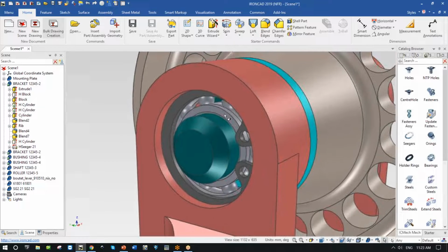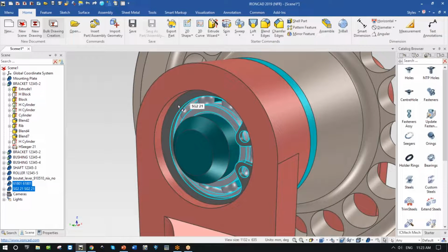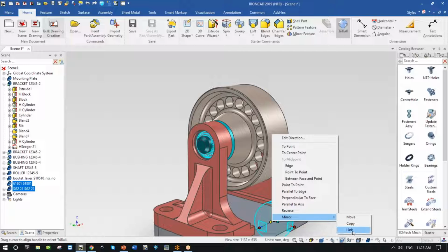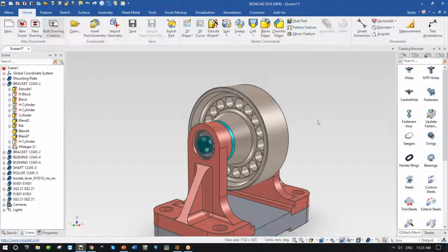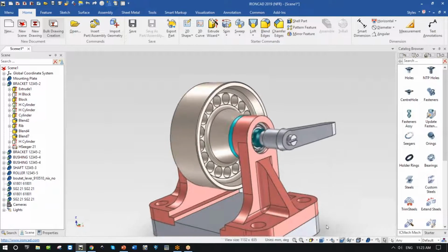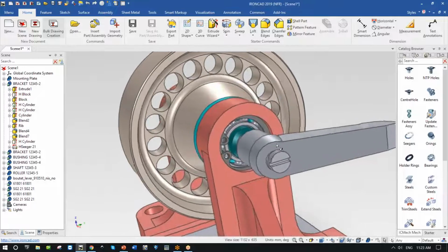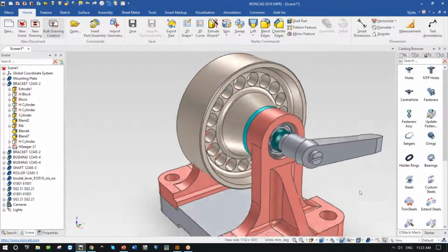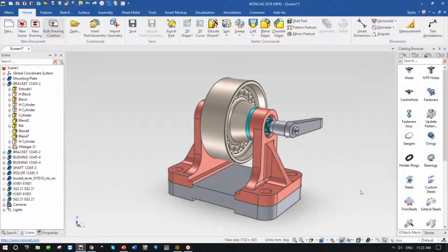I've got this on one side. Let's pick it up, highlight one, shift pick the other, grab this tri-ball, put the tri-ball right at the center of the part here, lock it into position. And what do I want to do with the tri-ball? Just give me a linked copy on the other side. So now what have I done? I've actually got these with the cut on both sides because they're linked. We're building a pretty cool assembly here.